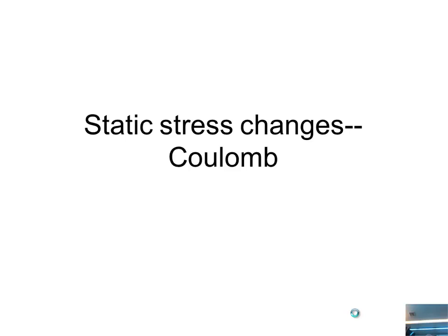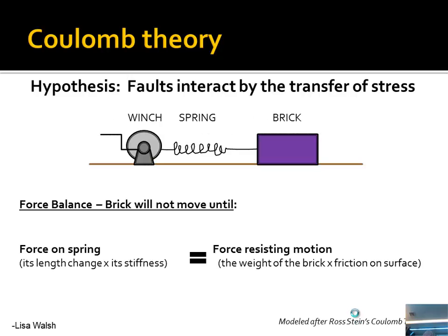So the important point is static. That means that there's no time in this. If you remember, if you have an earthquake and it's rupturing, it has lots of stress around the rupture that goes with the seismic waves. And so we don't compute the dynamic stress changes with Coulomb. It assumes that the earthquake is complete and over, and then we just look at the total change in the volume. And this is generally okay, although dynamic stresses can be much higher than the static ones. So for some situations, you need dynamic stress transfer models, but we won't discuss that here.